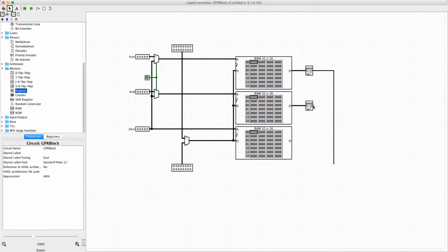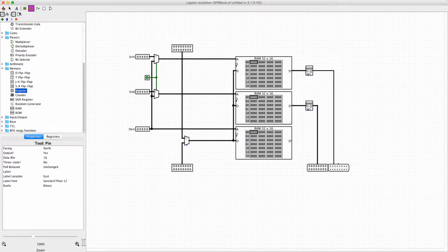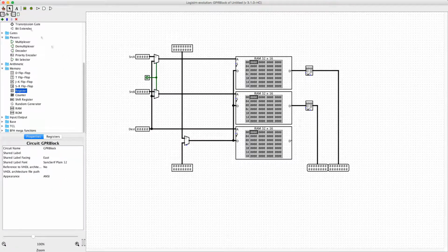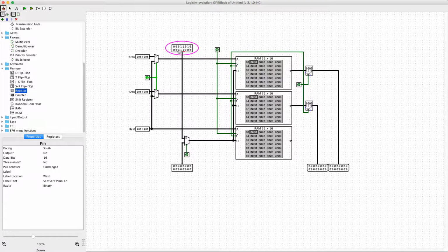Now, because of the way I'm implementing this, I'm having to use an intermediate register in order to simulate how data would be moved from one register to another without being modified in the process, and also needing to be moved to the ALU and then back into the GPR block without accidentally messing up what's already there. This method will take about 2 clock cycles to finish moving data from one register to another, keeping all 3 copies of the registers synchronized.